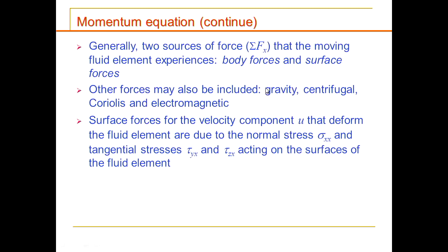But other force mainly includes gravity, centrifugal, Coriolis, and electromagnetic. This Guan put this too, but we never use it anyway, so just forget about it. Yeah, gravity is a thing. So in the CFD equation, sometimes you need to switch on the gravity. So if your domain has the y direction as the vertical position, your gravity is always minus 9.81 in your y direction. But for more information, ask those guys over there. They should be able to answer.